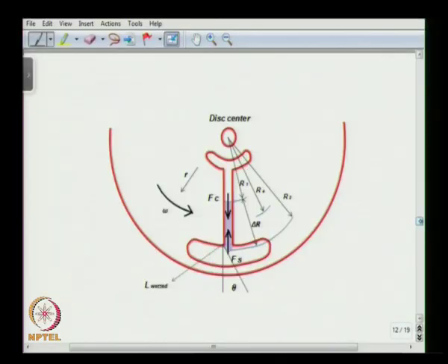So, the centrifugal micropumps work on the principle of the centrifugal force. Okay. So, normally the channels are carved on typically a CD configuration, and by using the centrifugal force, this CD platform is rotated, and when it rotates, because of the centrifugal force, the liquid moves from the center of the CD to the outside, the perimeter of the CD. Okay. So, this is the configuration of a typical centrifugal micropump.